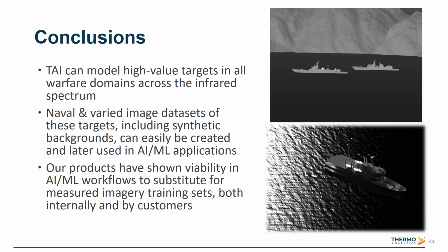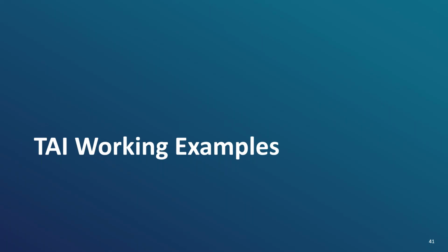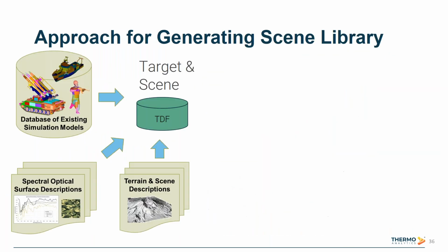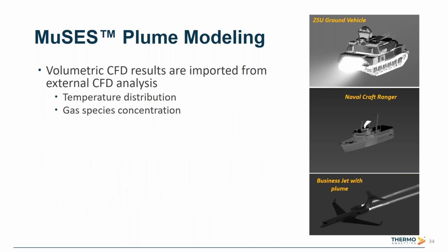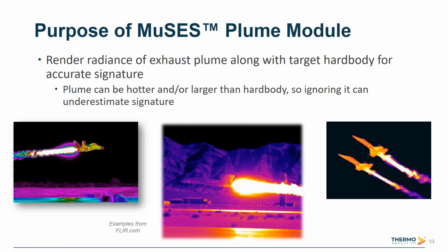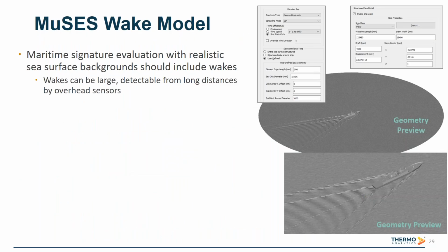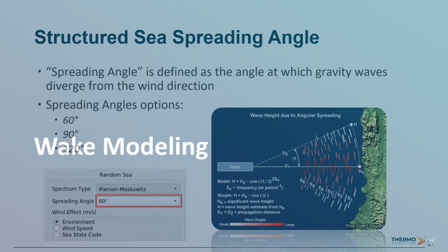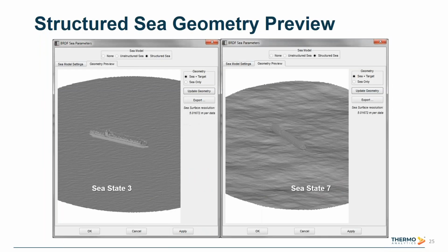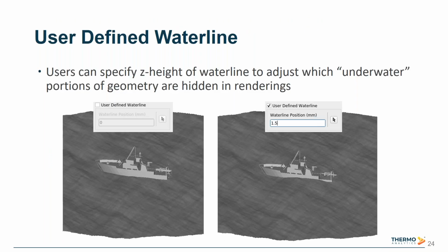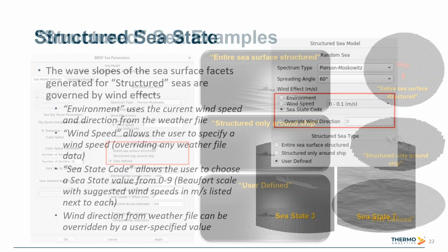Some questions here. Is it necessary to properly attribute heat sources under the waterline? Yeah, so it depends on what type of heat source and where it's located. I can actually go back to a slide that shows more part separation. Parts like the engine, especially in larger ships, are probably going to be underneath the waterline. That's very important because that heat translates up through the internal cabin and will be shown on the exterior surfaces above the waterline when you render images.